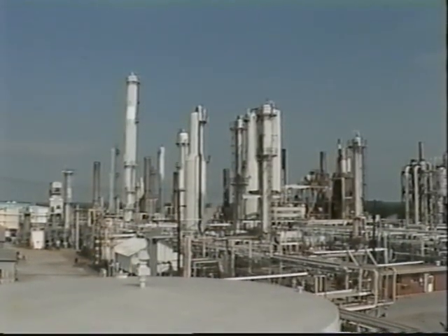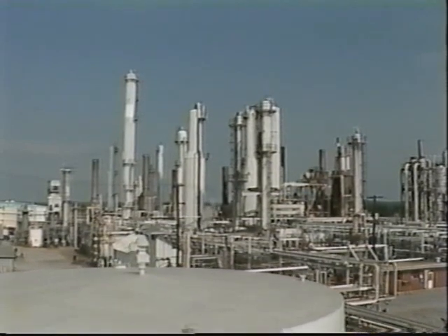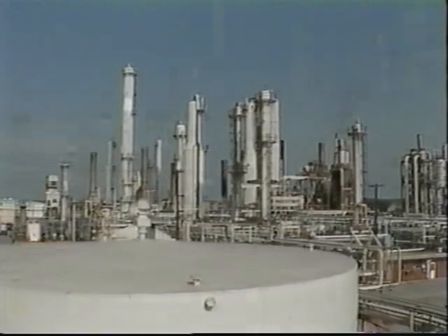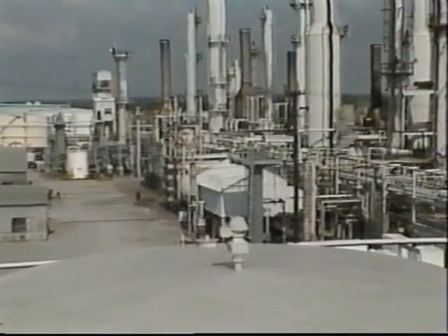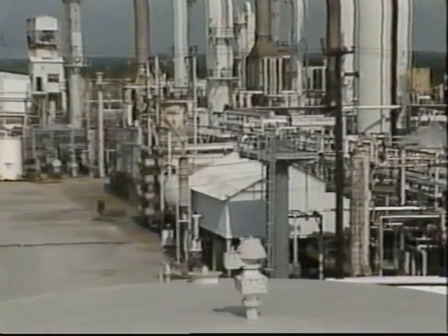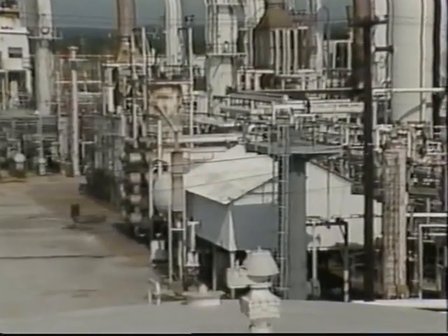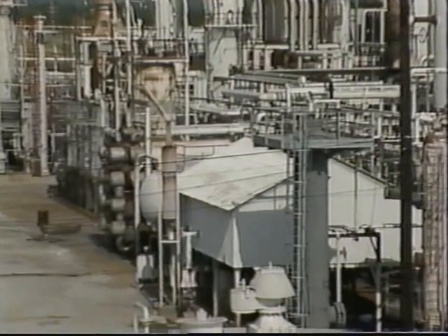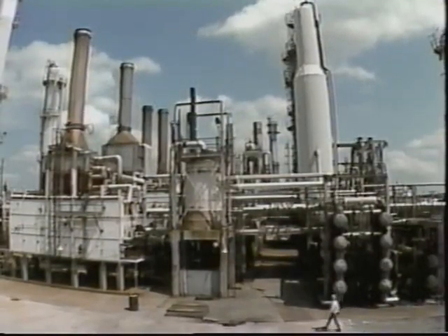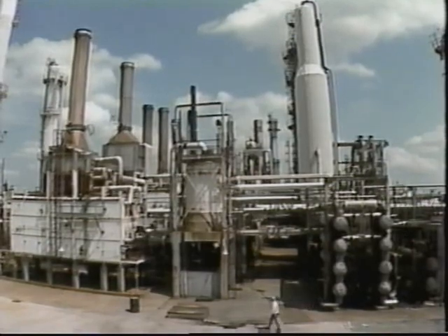If the reformate is off-spec, it may have to be routed and stored in a different area than normal until the problem is solved. Also, an increase in the hydrogen make flow rate means that more of the light gases are exported elsewhere in the refinery. The processes that receive the exported hydrogen will have to be informed of the increase so they can make the necessary adjustments in their area.